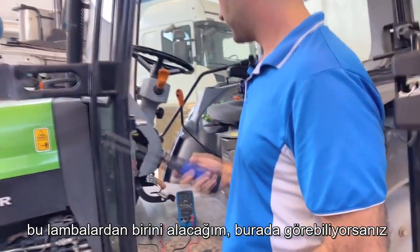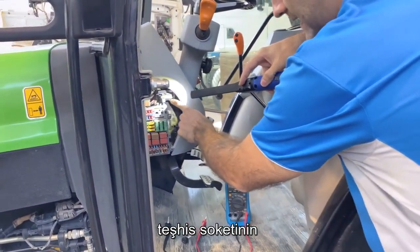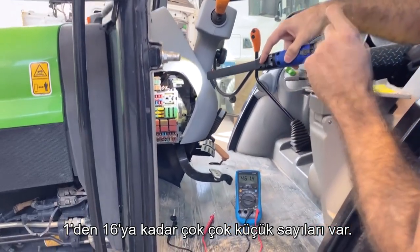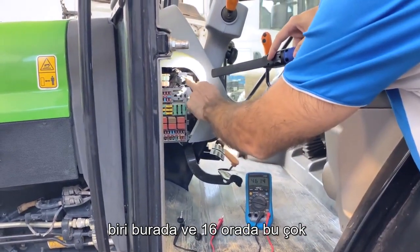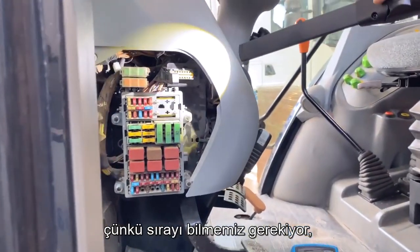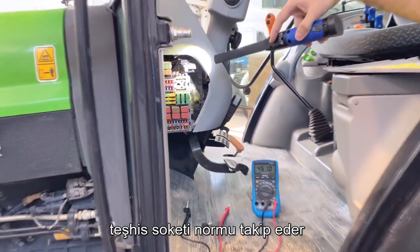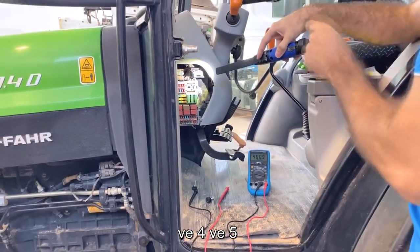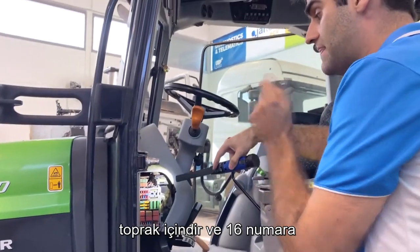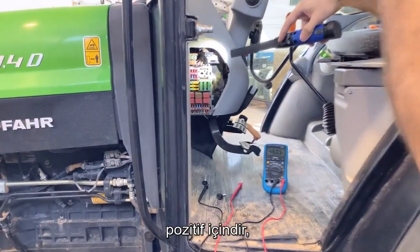Taking one of these lamps, if you can see here, the diagnostic socket has very, very small numbers, 1 to 16. 1 is here and 16 is there. That's very important because we need to know the order. If we know the order, most of the times the diagnostic socket follows the norm, and 4 and 5 are for ground, and number 16 is for positive.